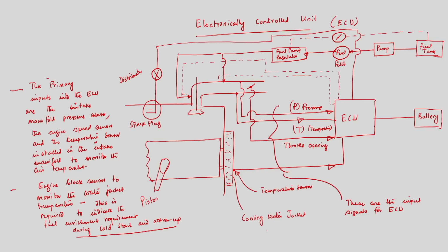Now, we can also see from the diagram that a pump is used to supply fuel from the fuel tank. So, we will have a fuel pump and regulator, but again depending upon the temperature and pressure of the air, if the requirement of fuel is less at that condition to get the desired output from the engine, then the additional fuel pumped by the fuel pump will be taken back into the fuel tank from the fuel regulator.